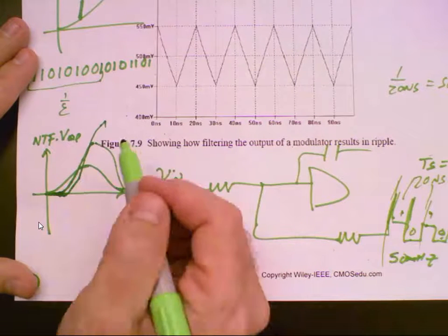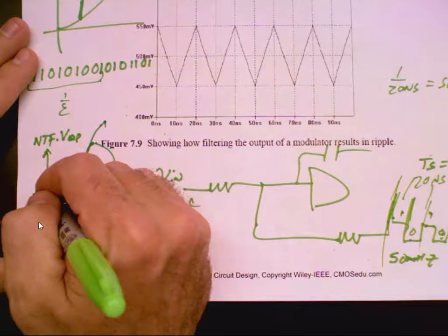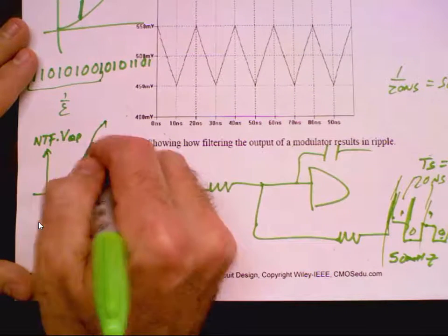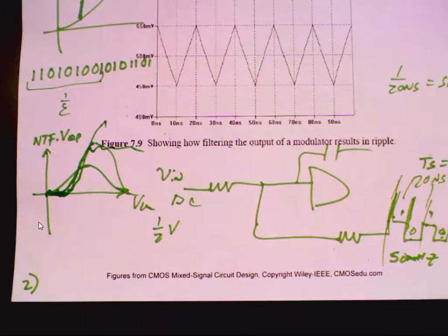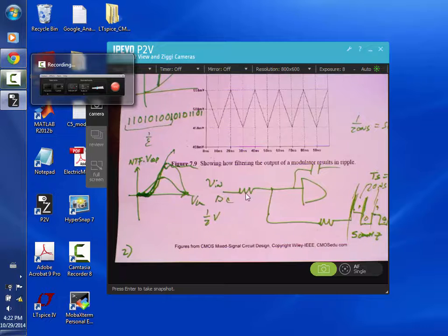So what they do in third and fourth and higher order modulators is they'll put some ripple in here, so this goes up and then is limited so it doesn't keep going without bound. If you try to use a simple third order differentiation, 1 minus z to the minus 1, in the noise transfer function, it becomes nearly impossible for single feedback loops to stabilize. We'll talk about, in a week or so, cascaded modulators, where we use cascades of stable first and second order modulators to get higher order modulators. Okay. Are there any questions there?